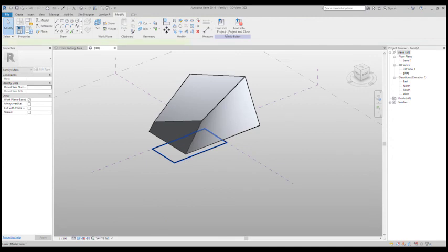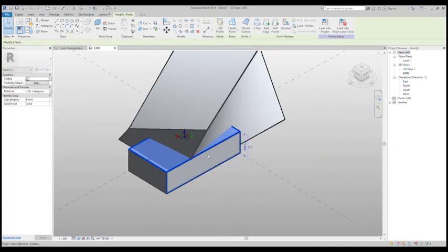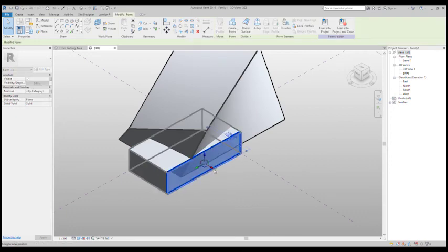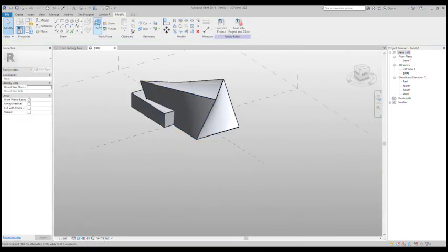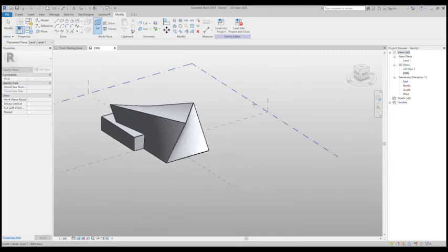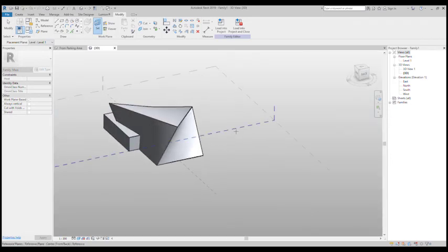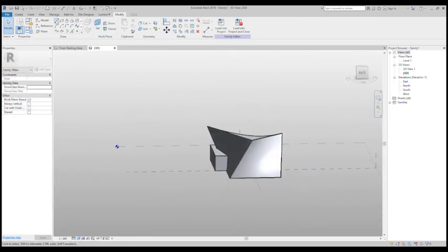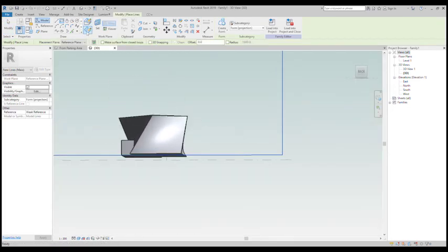Okay, extrude that up, sort of like a reception area for this building, and then maybe an exit or a view area here at the back. I'm going to draw that in elevation, so I have to set the vertical plane and draw on it by using this tool.